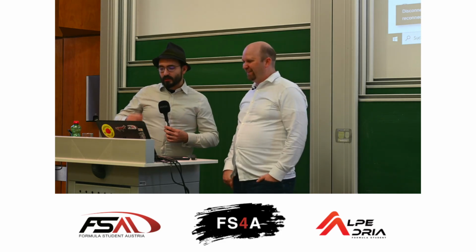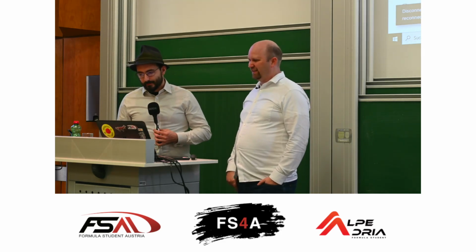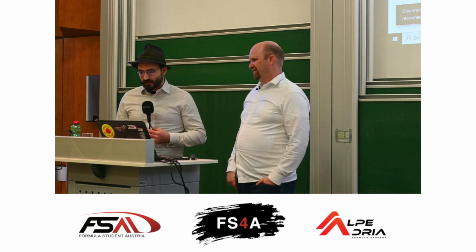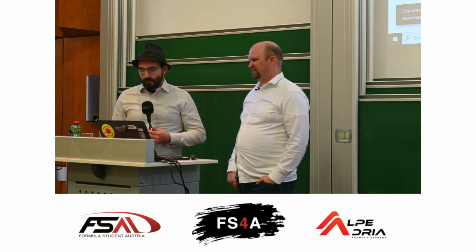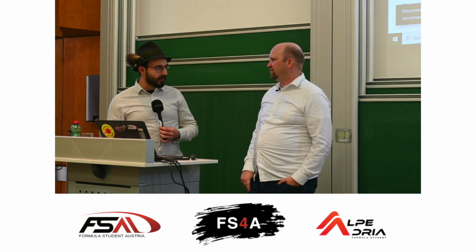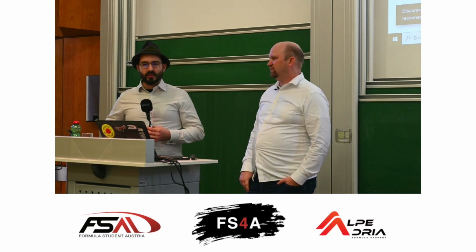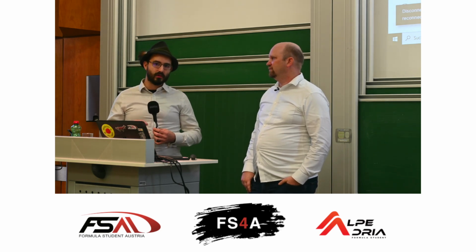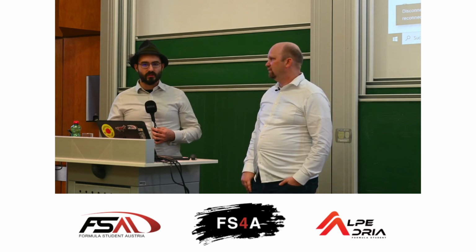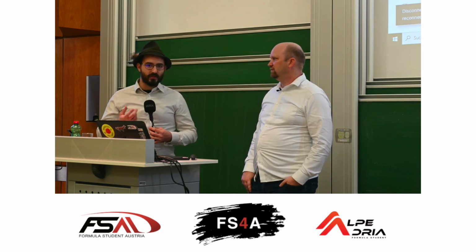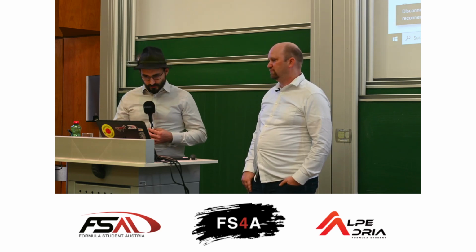There are quite a lot of rules about safety fasteners, which is chapter T10. In this case, we allow small fasteners to be used in any kind of application, but it still has to be a socket head cap screw or a hexagonal type bolt, because these are the only types of bolts where we say we can properly check them and these are proper fasteners.